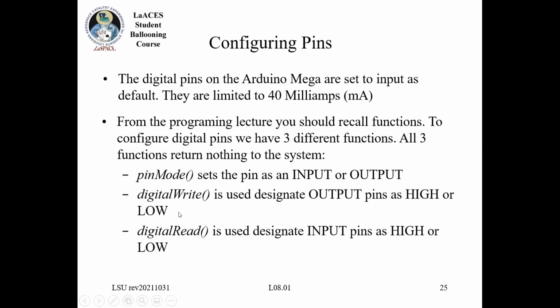Then if you have the pin set to an output, you call digitalWrite on that pin. What goes in the pinMode function is the pin number. And then digitalWrite will have the pin number and then the value. So you can set pin 4 high or pin 4 low.